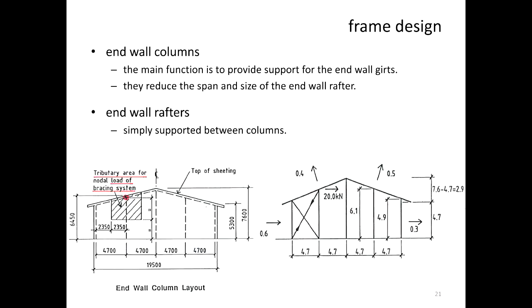So what I'm trying to explain is, when you look at your assignment question, there is a question for you to show what the geometry of the end wall is when we go to site. And you will see that the sections on that wall are usually much smaller. And the reason why we need those additional internal columns is because we need to provide more bracing in those walls, if you remember that.